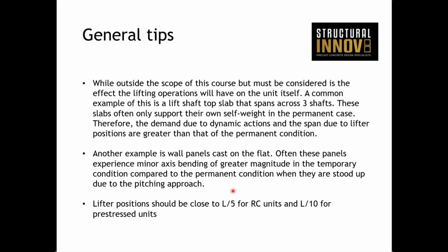And if you work out your forces, your bending moment diagrams, what that does is it keeps it more balanced, particularly for a rectangular section like a reinforced beam. Your hogging and your sagging bending moments will be almost balanced. So you're trying to just not put too much force on it in that case.